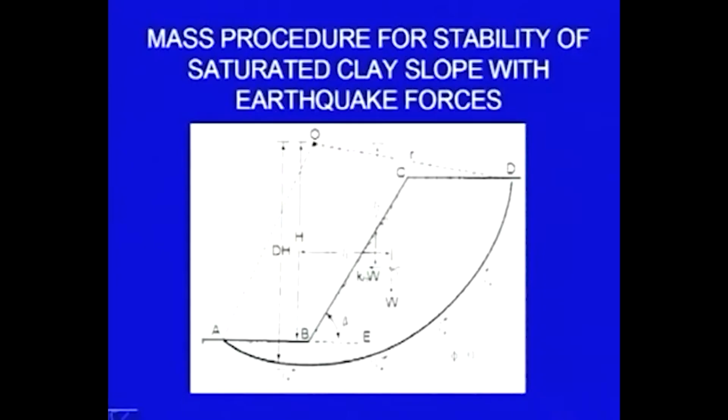We have to consider the moment about point O; about point O, this cylinder is trying to rotate. Resisting forces will be available from the cohesion which is acting along the periphery of the cylinder. This weight will be acting in the downward direction. So, the lever arm will be the perpendicular distance between these two lines.